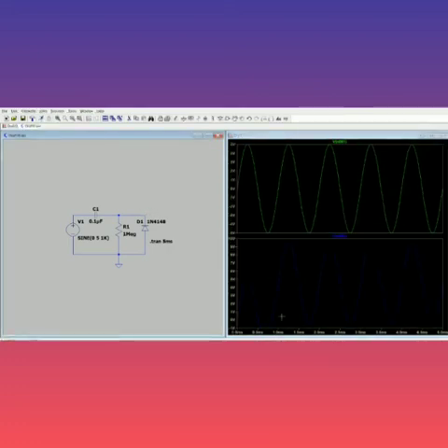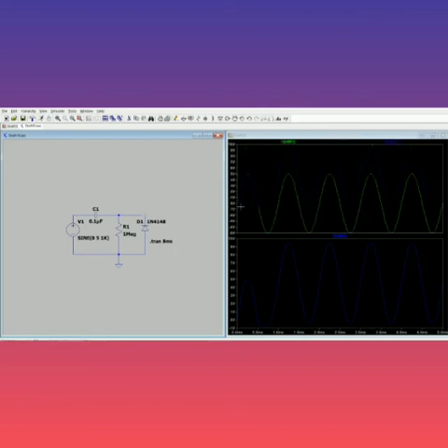So now you can see that it is clamped in your positive side. So for better understanding, I will click in the first and show you. Again, go to run option. Keep your cursor near the diode. So now you can see it has been clamped in the positive side. So double times 5 volt, it is doubled to 10 volt. So this is what is called as positive and